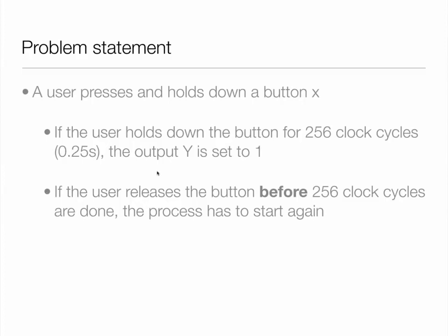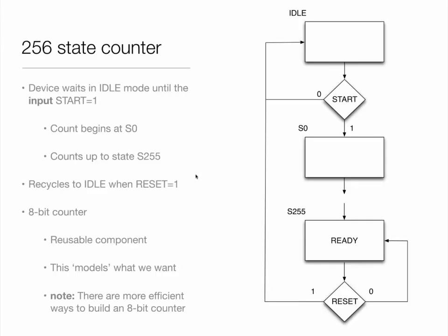So this is all about partitioning problems, breaking them into smaller bits. So not just combinational logic now, but sequential logic as well. Because smaller components are easier to test, we can often simulate them, write test benches, those sorts of things, maybe signal tap them. And then we have a chance that when we hook these things together, it's all going to work. Build a massive system, you're going to really struggle to get it to work. If a state machine gets too big, you probably need to partition it, which is its own subject, believe it or not. People spend their lives looking at that problem.